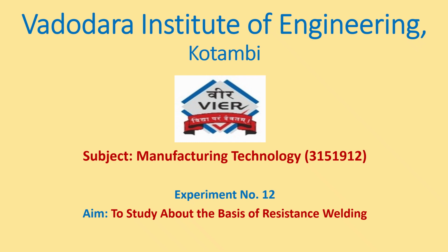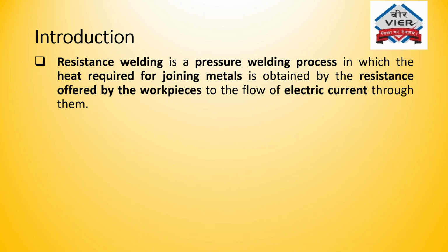Under the subject of manufacturing technology in degree semester 5 in mechanical engineering department, today we are going to see experiment number 12, which is to study the basics of resistance welding. Resistance welding is a pressure welding process in which the heat required for joining the metals is obtained by the resistance offered by the workpiece to the flow of electric current through them.